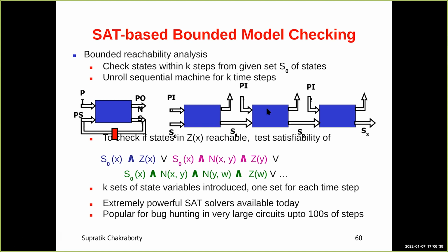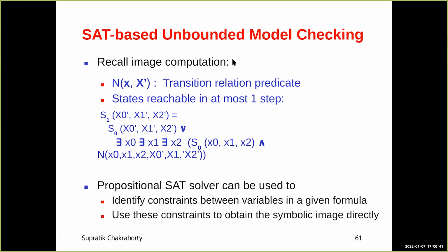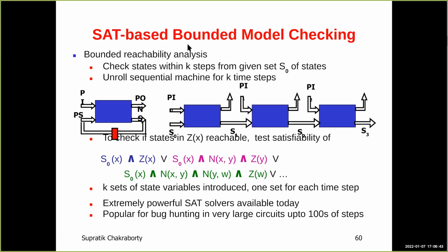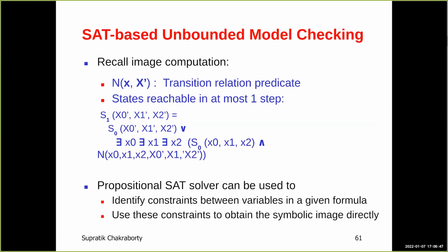And of course, you can represent these formulas using AIGs and then convert them to CNF. There are other SAT-based techniques. This is called SAT-based bounded model checking because you're bounding the depth up to which you want to see. There is also something called SAT-based unbounded model checking, where you basically take the same formulation that we use for BDDs,